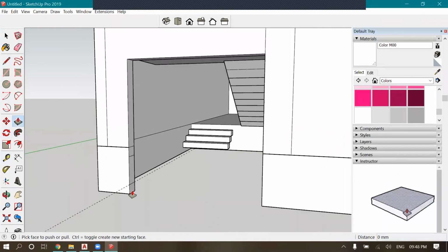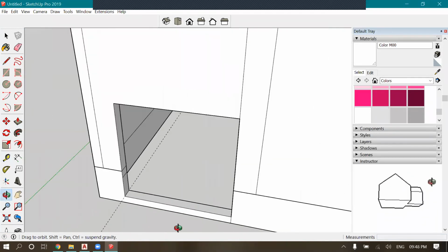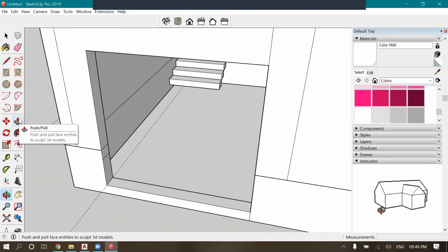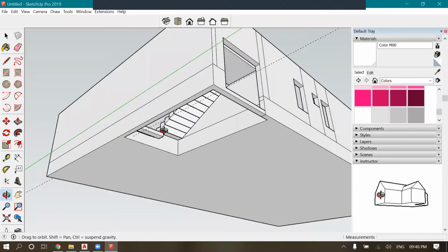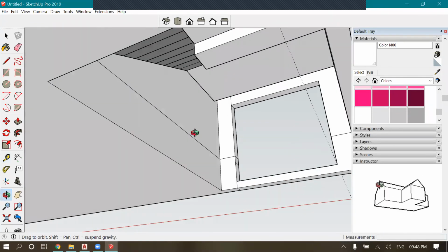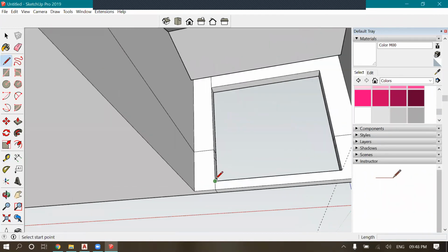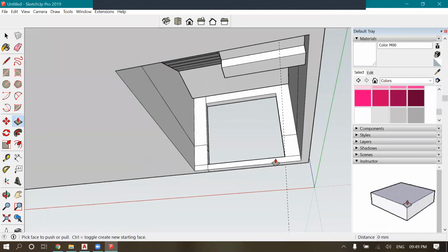Just drag this part. It will be in the base section. I have just deducted 160 from it. Let's say, what's the height? In this 2260 we have 2100 for our door height, and 160 for the base lap that I had provided by mistake. So what we need to do is just drag them.